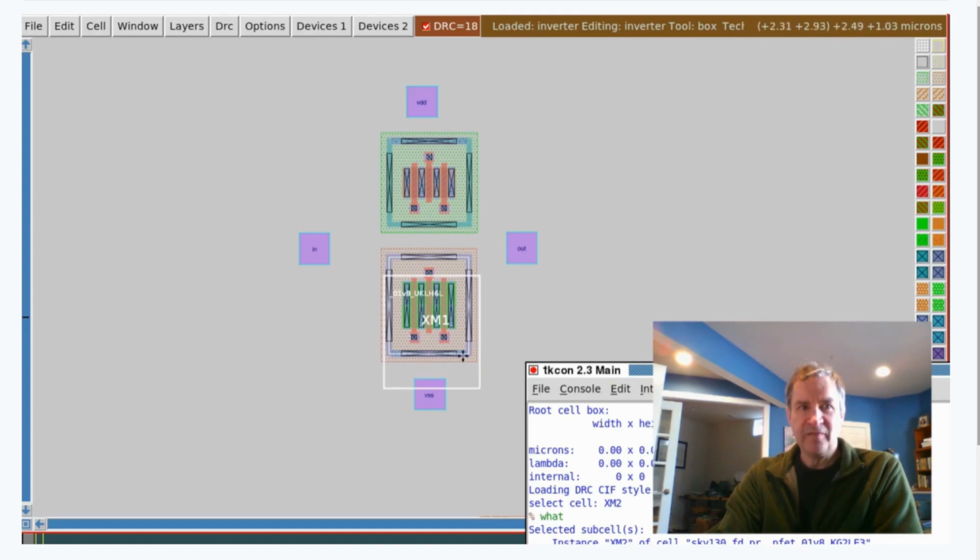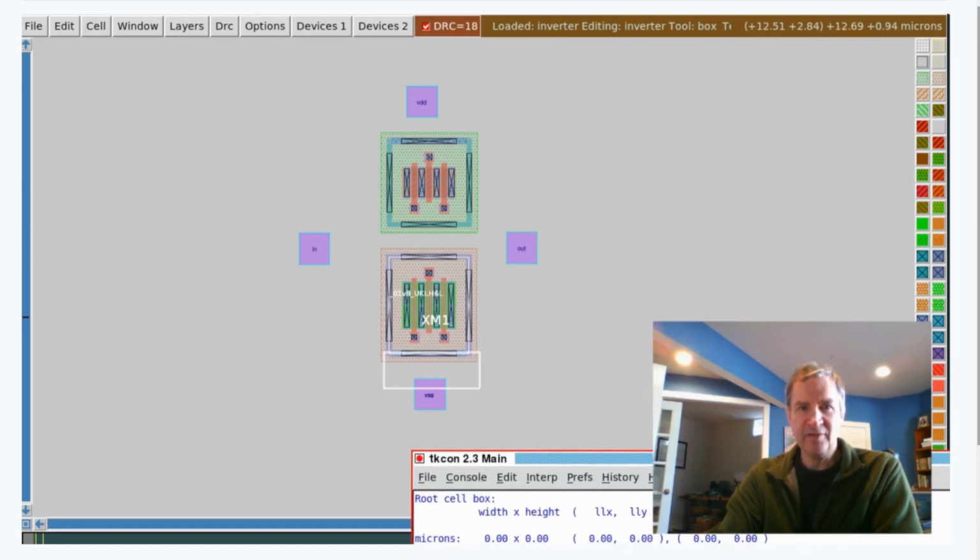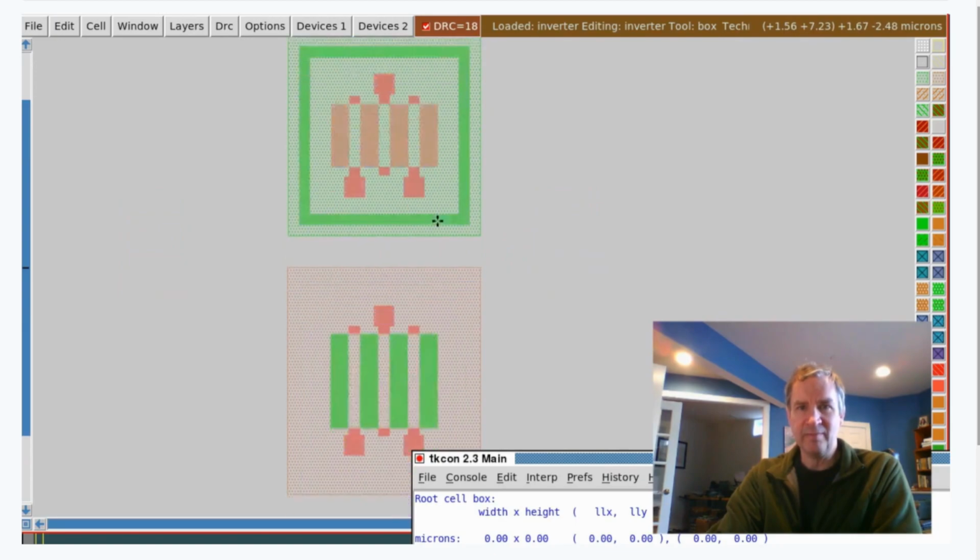To wire, just follow what I'm doing here in the layout. I want to connect the VSS pin to the bottom rail, so I put the cursor box covering the pin and the NFET contact, then hover the pointer over the metal 1 area of the pin and click the middle mouse button to paint that type into the cursor box. I do the same thing for VDD. VDD and ground have to go to the transistor sources, so I'm going to connect them up like this.